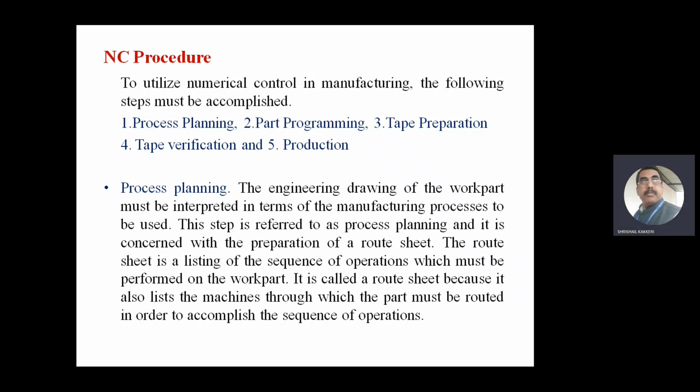Correct, no? And please tell me, what is this important term which I told you, tape verification. You are going to use a foam or wood or low cost material, or simply we are going to run the tool without putting the material and feel satisfied. Okay, if my program is correct, then I can run it on the actual material for the machining.